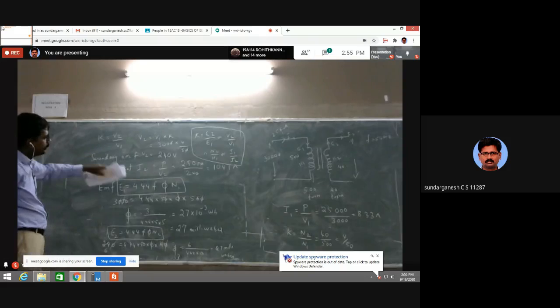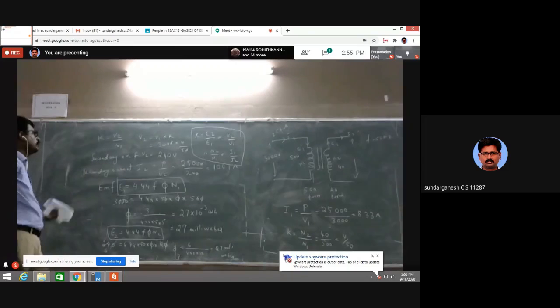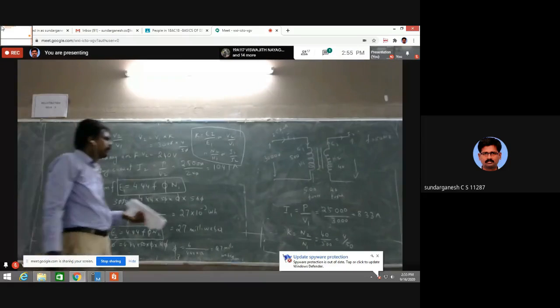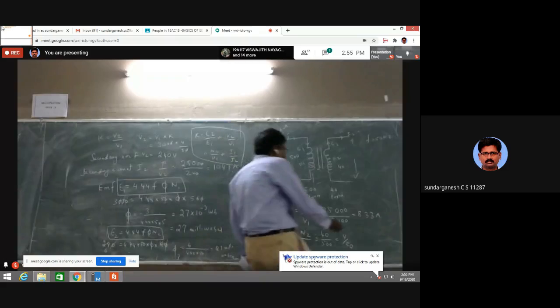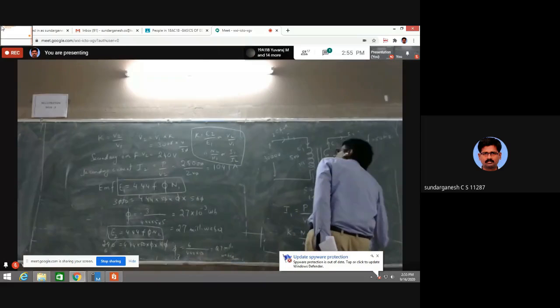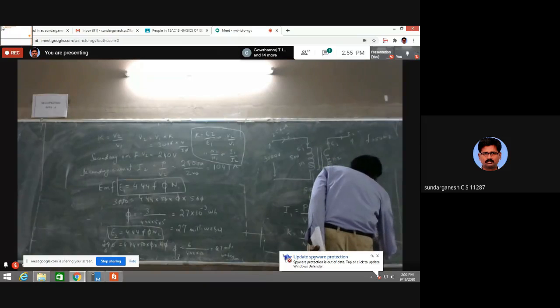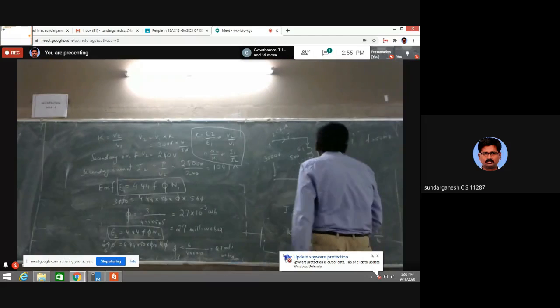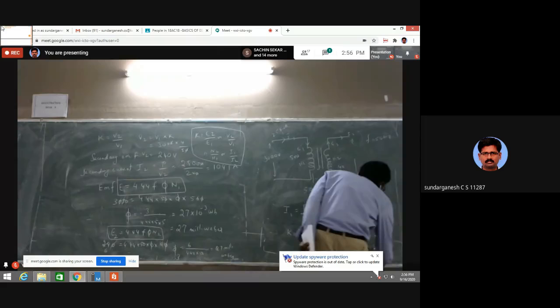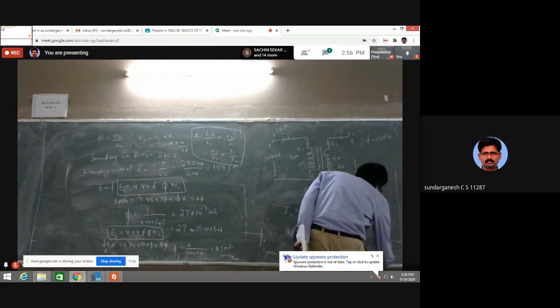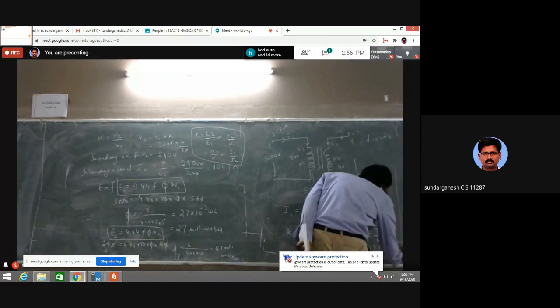So instead of finding EMF and then finding the current, I can directly find it here. I want to know I2. So I2 is I1 by K. So I1 is 8.33 divided by 4 by 50. So this will become 104.1 amps.